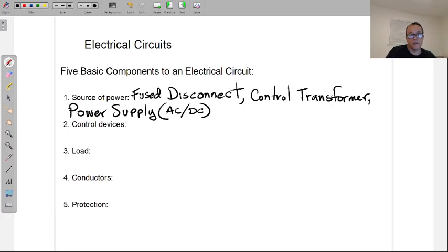Are we ever converting DC to AC? Not for control use. All right, first, because where are we getting this DC power source? No building I know has DC power coming to it. Even if the building had solar panels outside that are creating DC power, they're usually providing AC power for the building. So for that reason, it's always an AC to DC power supply system.